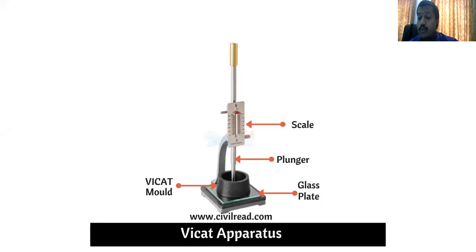That is why we have to make sure we prepare our cement paste within 3 minutes only. Very concisely, very precisely, we have to mix it. So we are going to prepare our cement and water paste within 3 minutes.